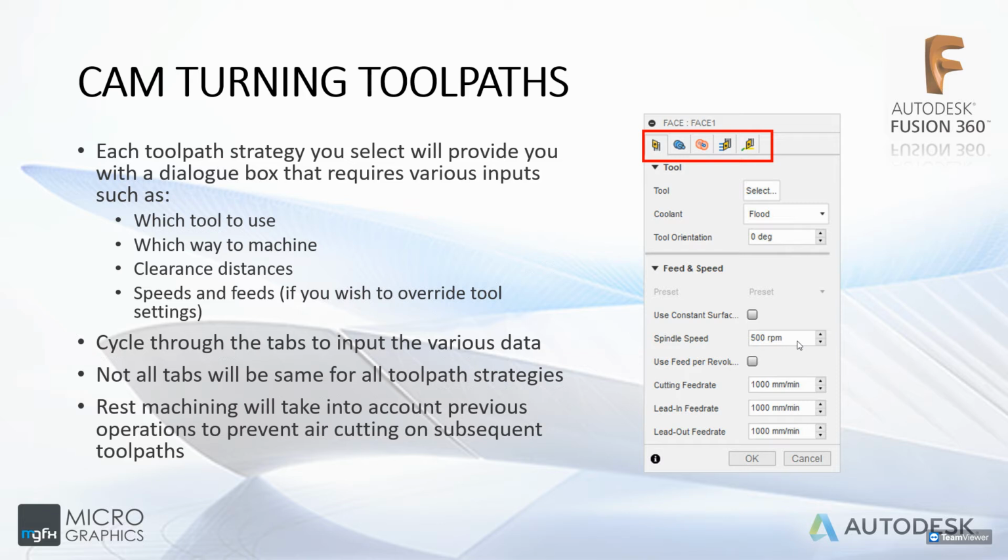Okay, you can also define your clearance distances. So the radius at which the tool must be away from the stock material in order for it to rapidly move to ensure that it's quite safe and doesn't collide with anything.